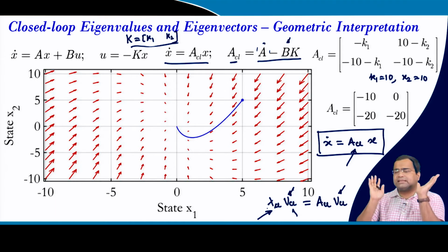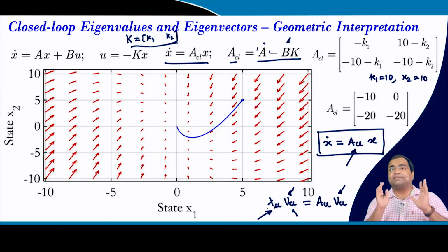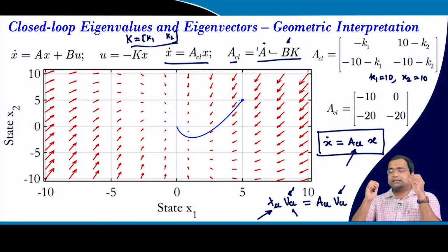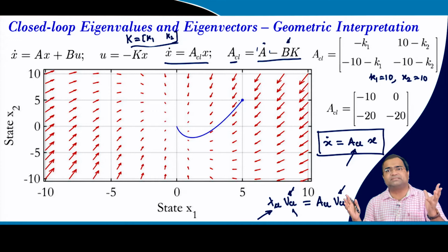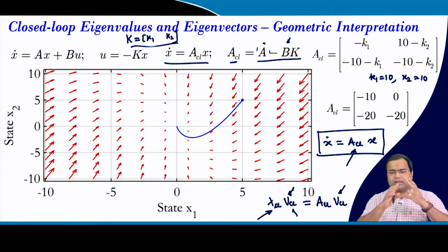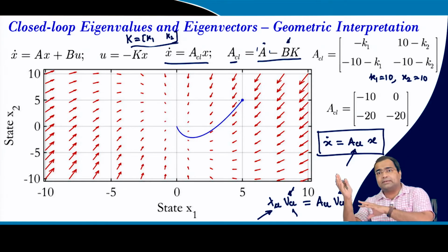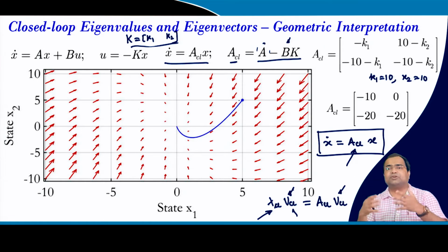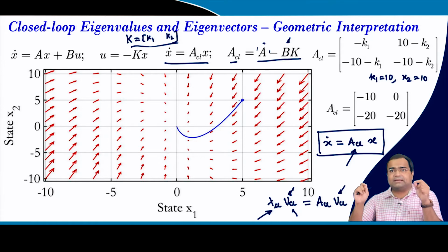So, if we cannot place the eigenvector, the problem will be the shape of the trajectory, because we have discussed that two subsystems can have the same eigenvalues but completely different eigenvectors. That means if we make a linear transformation of the system, transforming this closed loop system to another plane, it is like an image: if we change our view angle, you will see the nature is different, right.